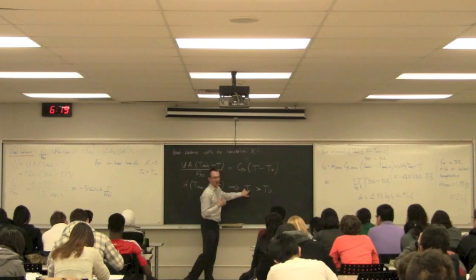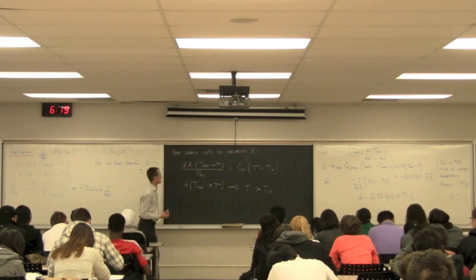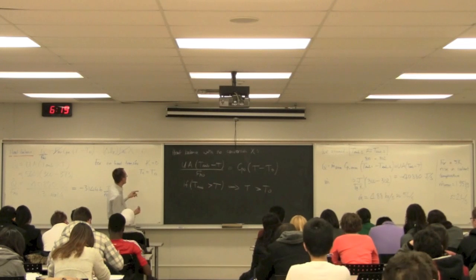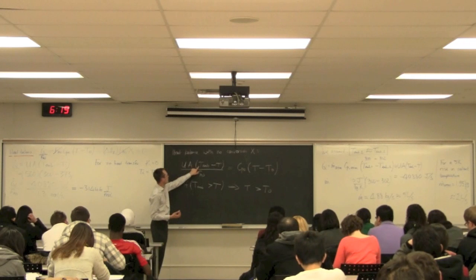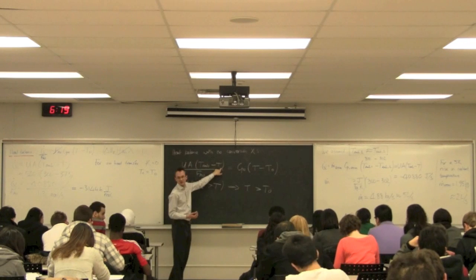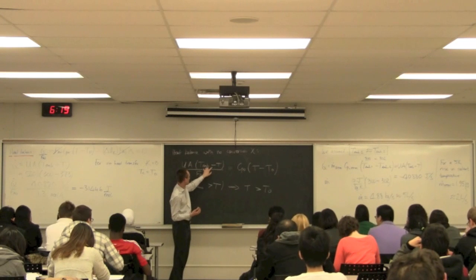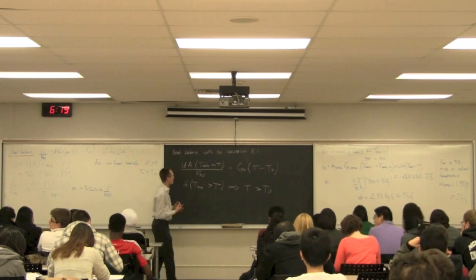So that must imply, we expect that my temperature leaving must be greater than the entry temperature. That's a great way to make sure that you don't have your signs flipped around. Sometimes people write this equation as UA times T minus T ambient. That's a very good check now. We can quickly make sure that my signs do make sense and match up with what I expect.